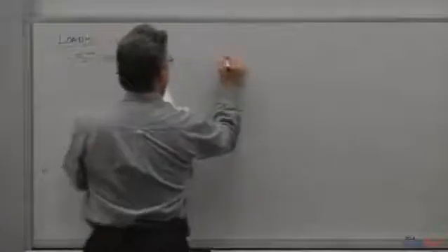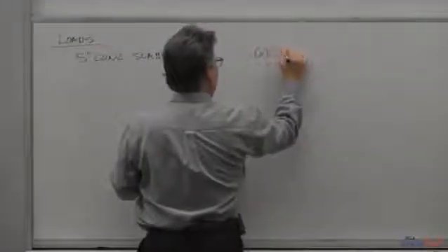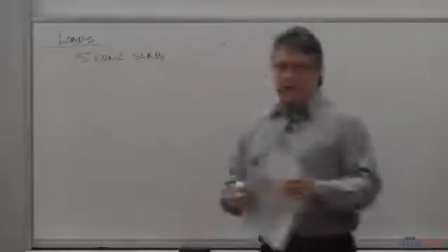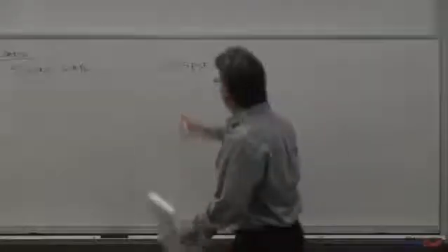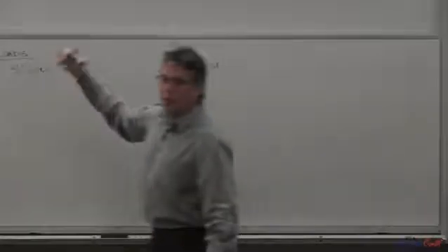The first thing in anything that you're going to design, steel, wood, concrete, pre-stressed concrete, you'll need a loading criteria sheet. If you guys saw Brian's calculation books, the first thing was the load criteria sheet in everything we ever do. This is the way most practicing structural engineers will do the load criteria. Regardless of what it is, the slab, the beam, the column, the walls, you break that into a pound per square foot on the building. I'll discuss why that is in a minute.